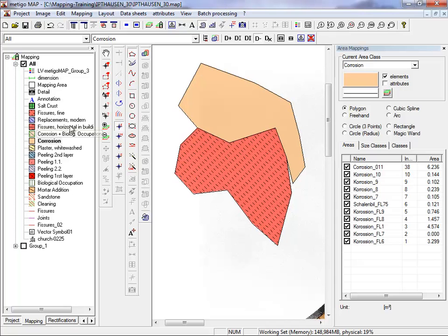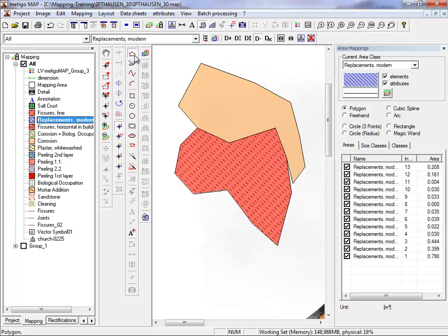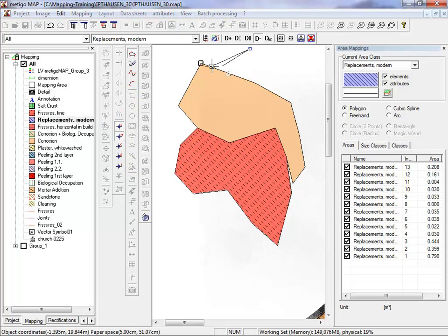We switch to the third class and activate the object snap mode midpoint. If the cursor hovers now on a line, we can choose between the indicated endpoint and midpoint. Snap to the midpoint, endpoint, midpoint.